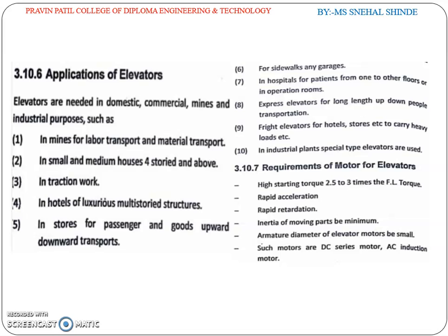Requirements of motors for elevators. High starting torque, 2.5 to 3 times the full load torque. Rapid acceleration, rapid retardation, inertia of moving parts be minimum. Armature diameter of the elevator motors be small. Such motors are DC series motor, AC induction motor.